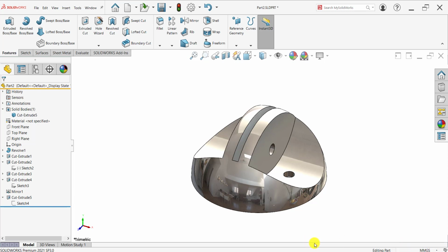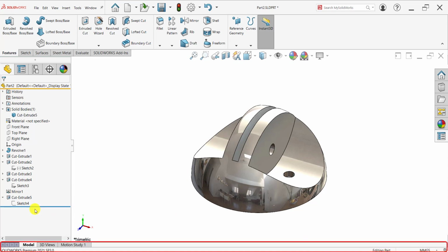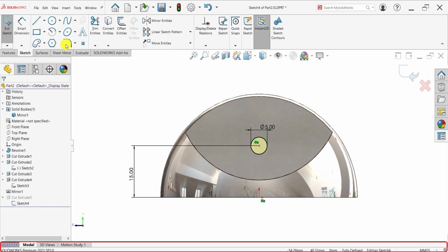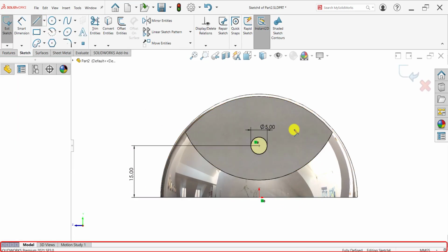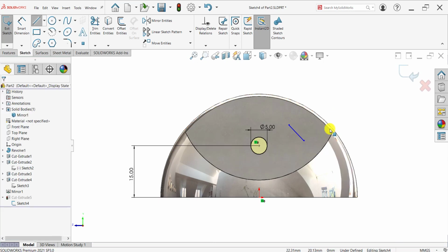At the bottom, we have the Status Bar. The Status Bar non-intrusively communicates SolidWorks information back to the users, and it contains some interactive options. In the status bar, we have a rebuild icon. If you change a sketch or part that requires the rebuild of the part, just like the one here.